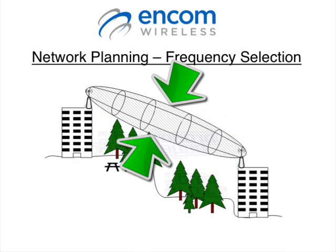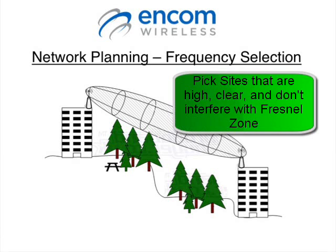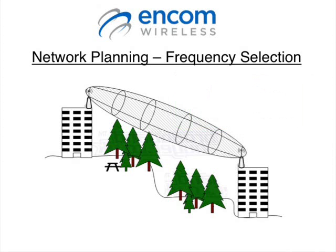This is why we would always aim to have the highest height possible, as well as a clear line of sight, such that we're not interfering with our Fresnel zone. As you can see in the picture, there are trees in the way, but they are not blocking a significant portion of our Fresnel zone. Always try to maintain a clear line of sight in your site selection.